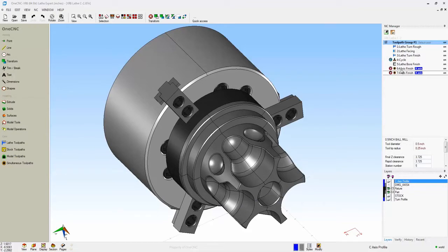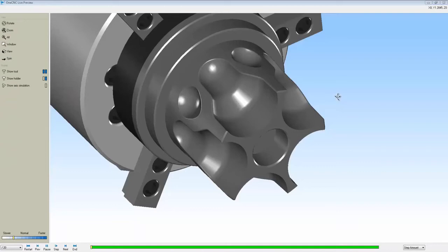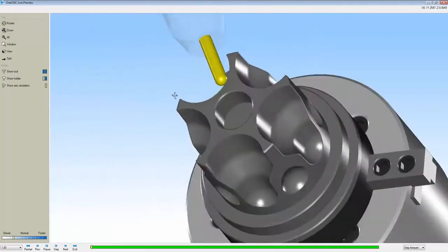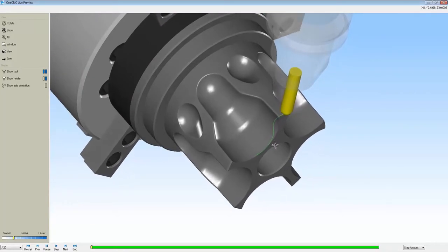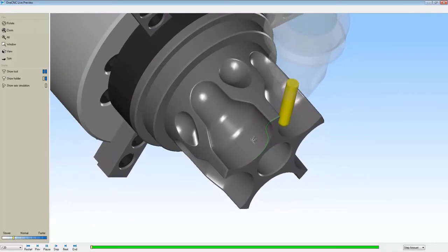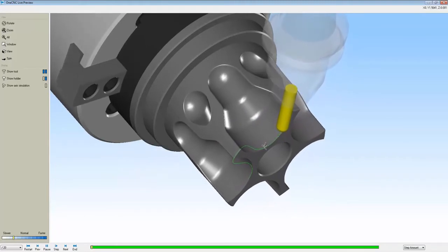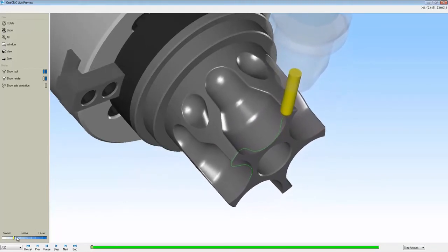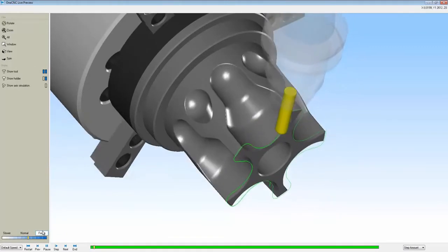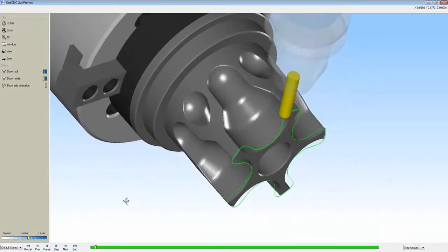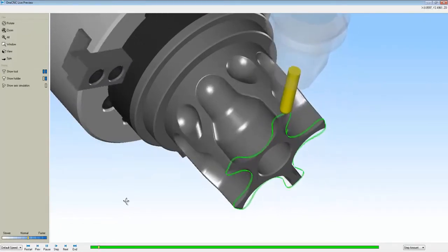Alright, so to demonstrate, why don't we take one of these machining operations into Preview. Now in this first example, I have the C-axis full set to machine around the part. And what you do is you specify, of course, the feed rate, the speeds, and so on, but you also specify the step over as well. I'm going to speed this up just a bit. And what I've done is I've specified a 20,000 step over on this. So this is called the C-axis full machining, and we're cutting around the part.